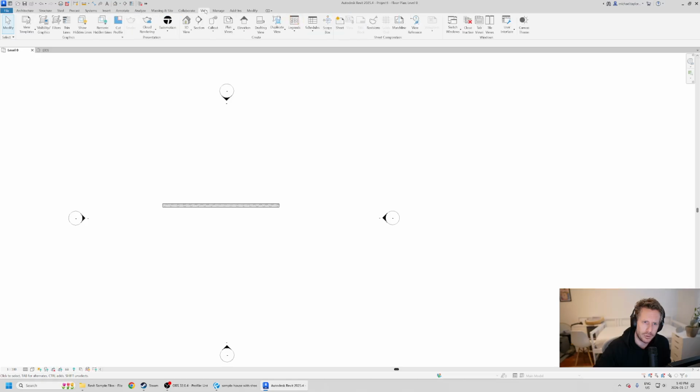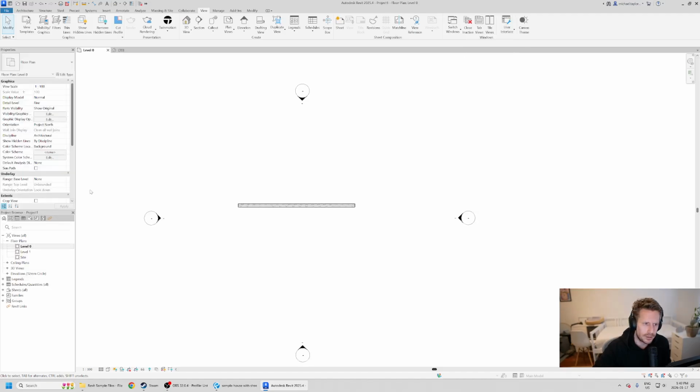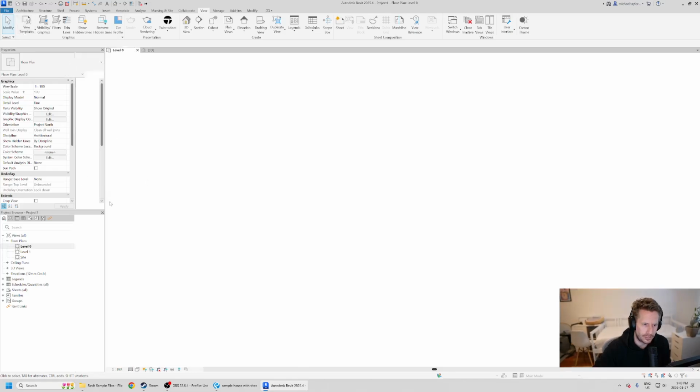Come over here to view. We're here to view user interface, and you're going to go ahead, you're going to hit that little checkbox, and it's going to give you back your project browser. And down here, hit that little checkbox on properties. And now we've got our properties and our project browser back.